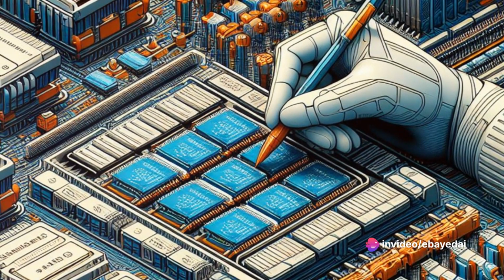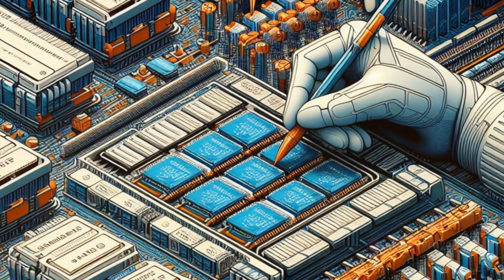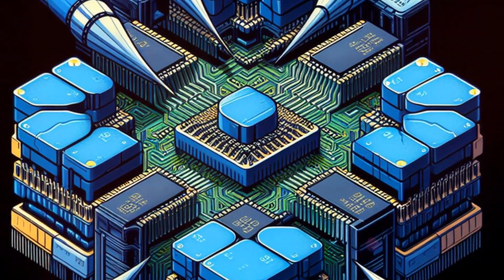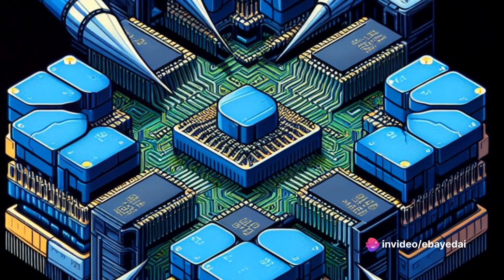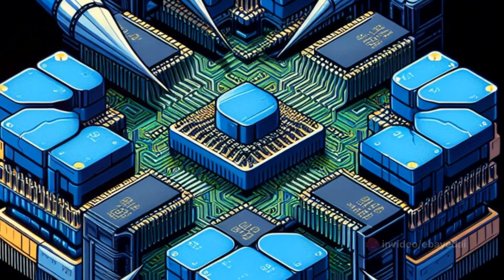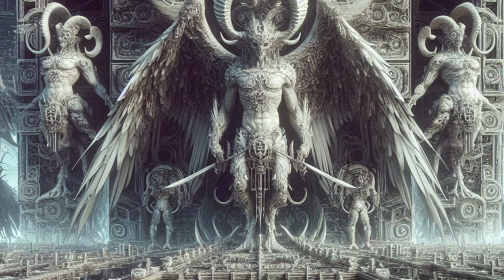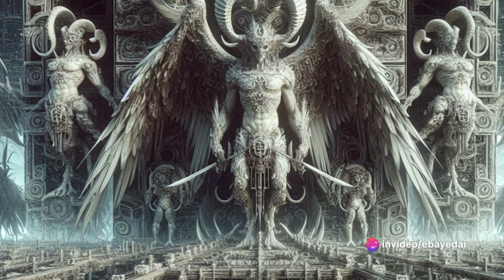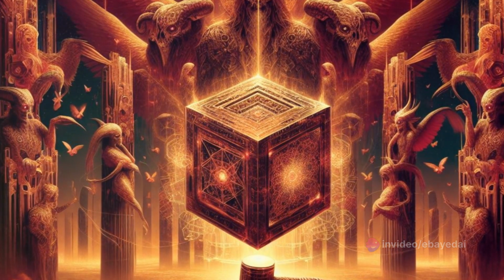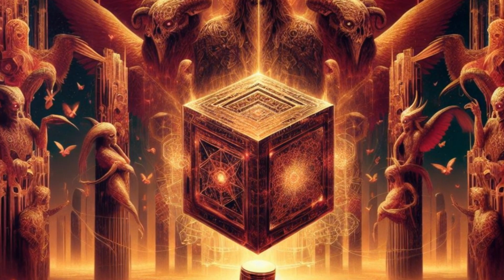Memory cells, blue squares in both illustrations, are further organized into matrices and addressed through rows and columns. A memory address applied to a matrix is broken into the row address and column address, which are processed by the row and column address decoders, in both illustrations, vertical and horizontal green rectangles respectively. After a row address selects the row for a read operation, the selection is also known as row activation. Bits from all cells in the row are transferred into the sense amplifiers that form the row buffer, red squares in both illustrations, from which the exact bit is selected using the column address.